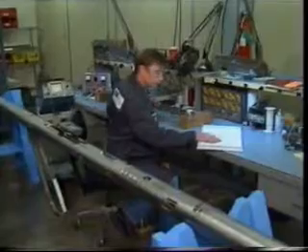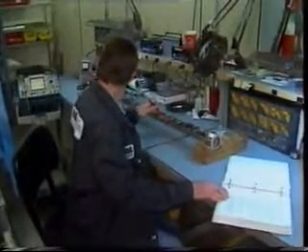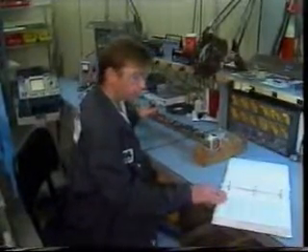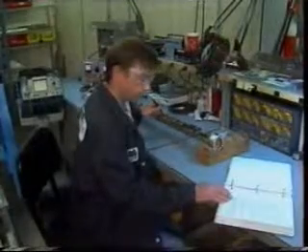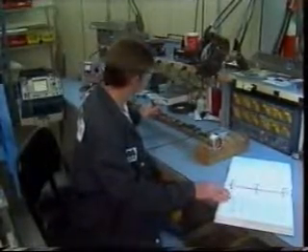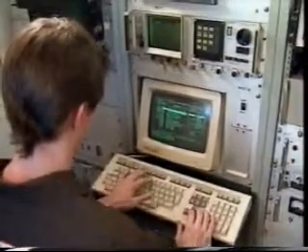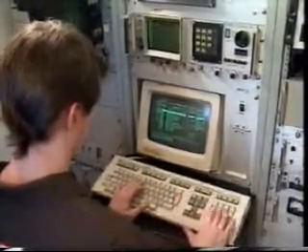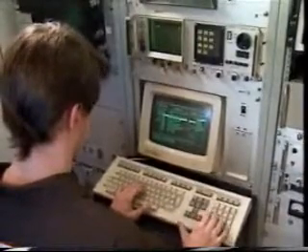Since these tools measure voltage changes caused by varying resistivities, it is relatively easy to reproduce a unique voltage with precision resistors and a stable current source in the tool. In fact, all these tools have built-in calibration resistors, which are used by the engineer to determine a low-end and a high-end calibration point by which the logging system response is then determined. Once calibrated, the tool system will respond to ranges of resistivities encountered in logging.